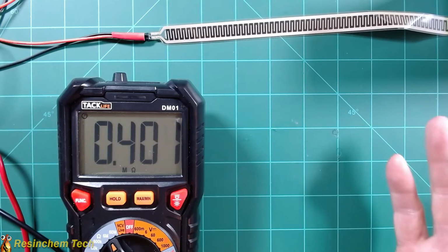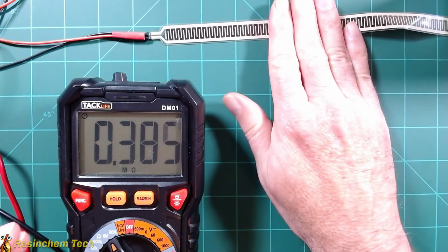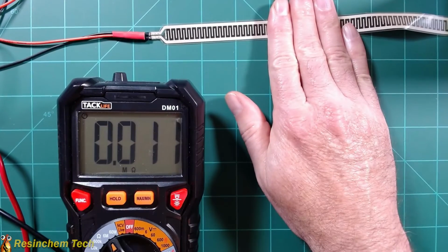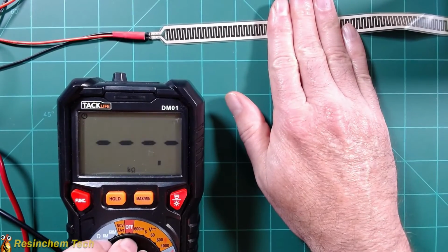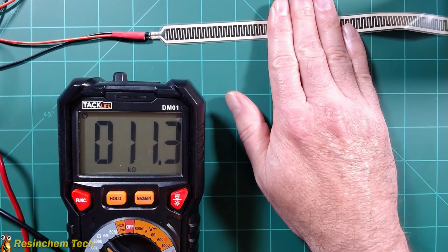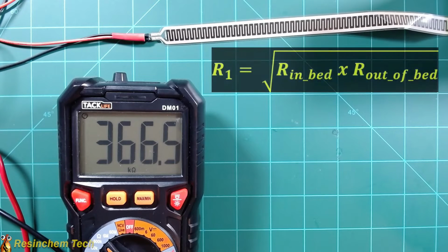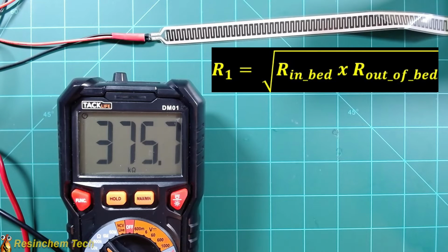But what you want to do is get some resistance readings with the bed unoccupied, and then get into bed, and there's a good possibility you may actually need to change the scale on your multimeter. And you want to take a dozen readings or so of both, occupied and unoccupied. And we're going to kind of average those together to drop into a calculation to get us at least a starting resistor value.